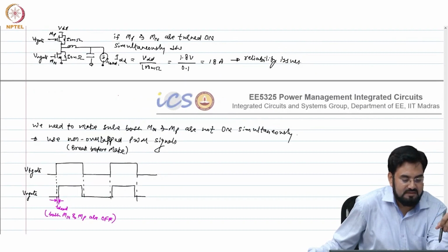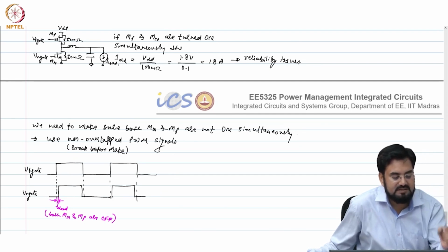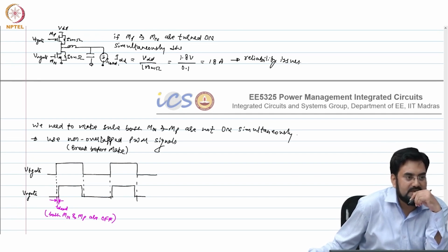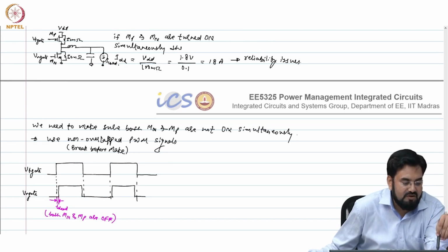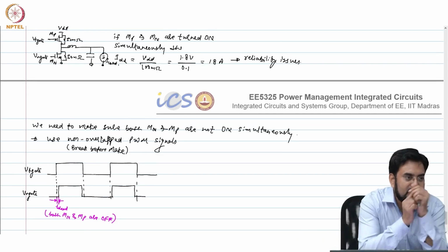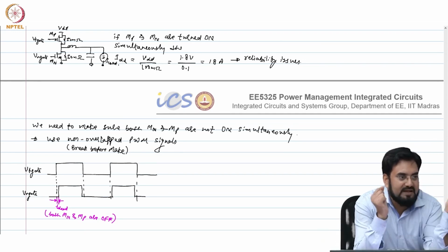I mean, the capacitor will start discharging, but what would happen to the inductor? And the inductor's other end is open, huh? No, high resistance is there, but think about all of a sudden you turned off both the switches. Inductor will maintain the current.